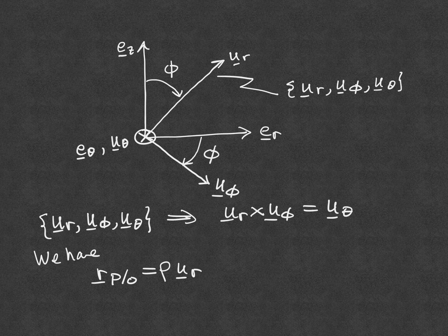And we're going to call that frame reference frame C. So given that this basis UR, U phi, U theta is fixed in reference frame C, in order to obtain the position, velocity, and acceleration as viewed by an observer in reference frame A, because this basis is fixed in reference frame C, we need to apply the transport theorem.